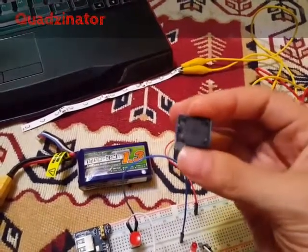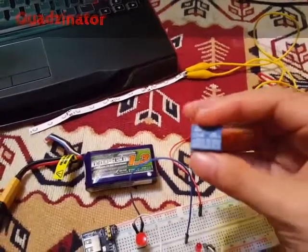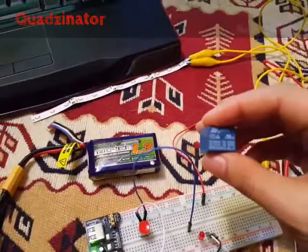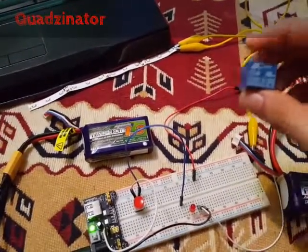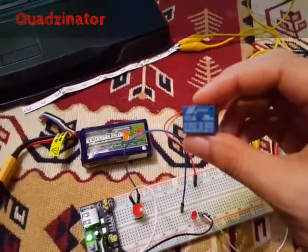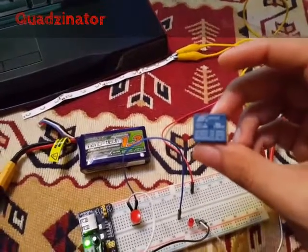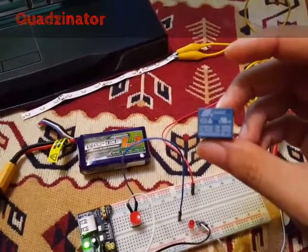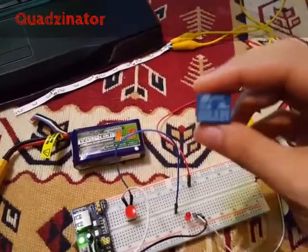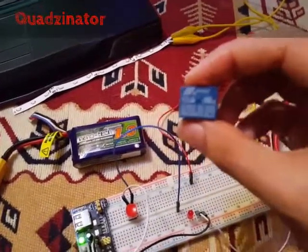What is a relay? Basically, a relay is used in many applications. Why I'm presenting it on my channel is because we're going to talk about it and use it in robotics and further robotic applications. So what does a relay do exactly? A relay enables us to control a high voltage circuit using a low voltage circuit, something like a switch.